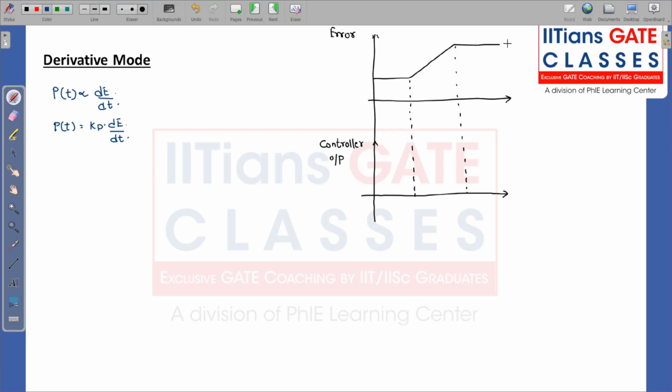Suppose my error is something like this, then we know that for a constant, if I take the derivative, it is going to be 0. Now derivative mode is called anticipatory. Why so? Suppose this time is T1, this time is T2. Error at T2, let me assume it is E2, and error at T1 is E1.